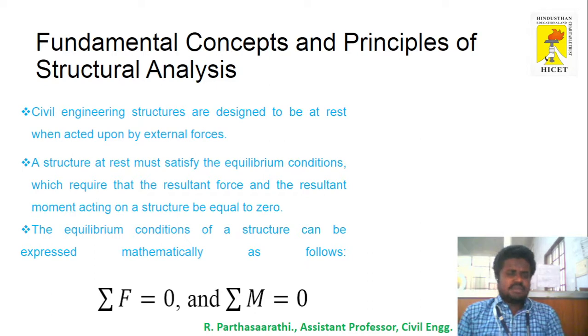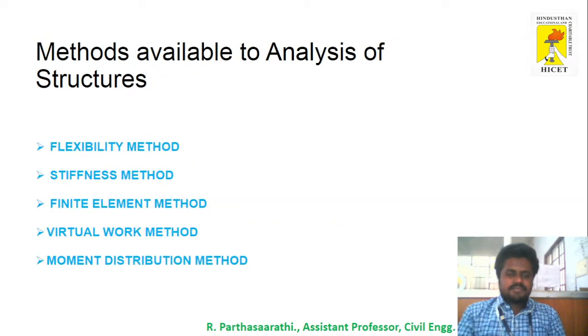So, the fundamental concept and principles of structural analysis. In civil engineering, structures are designed to be at rest when acted upon by external forces. A structure at rest must satisfy the equilibrium conditions: summation of forces equal to 0 and summation of moments equal to 0. We have vertical forces and horizontal forces acting on the particular structure. If we can satisfy the three equilibrium conditions, it is a determinate, stable structure. The methods available to analyze a structure include the flexibility method, stiffness method, finite element method, virtual work method, and moment distribution method.